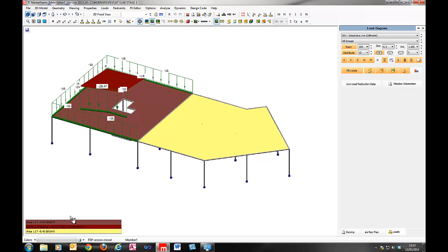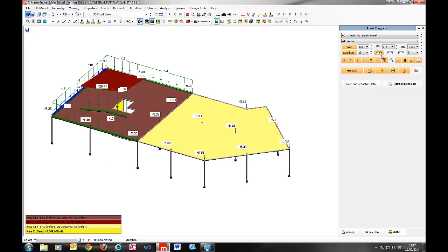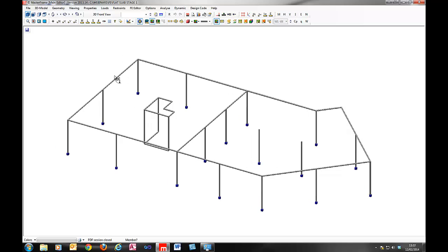And we may have missed something in this little example. It seems we've got our density button, the D button, not pressed over here, so that didn't include the density. So now we've got our density values coming in, and we can validate what our slab self-weights are and such as well. Okay, so a good idea at this stage is I want to actually make this into a multi-story